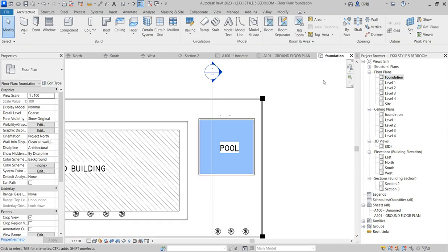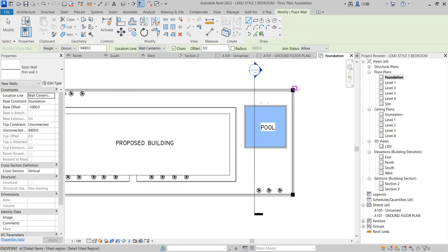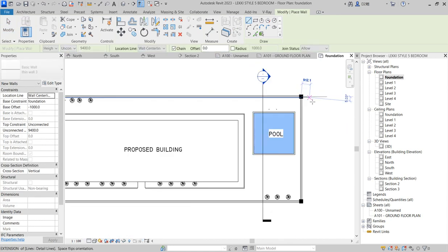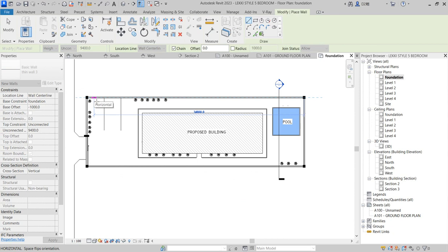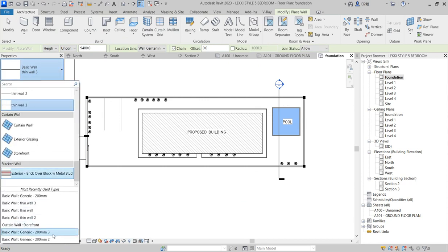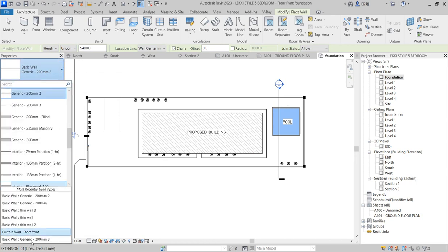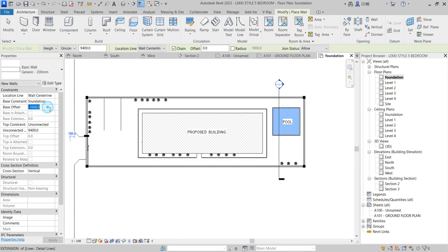So the next thing is to adjust the fencing. So probably for now we are just going to create a fencing. Just click here. Sorry, just say select artificial, then go to, I think, this particular one. No, the basic. Okay, this is the basic. So you are going to change the base height to 0 to the minus. Okay, when foundation just say 0.